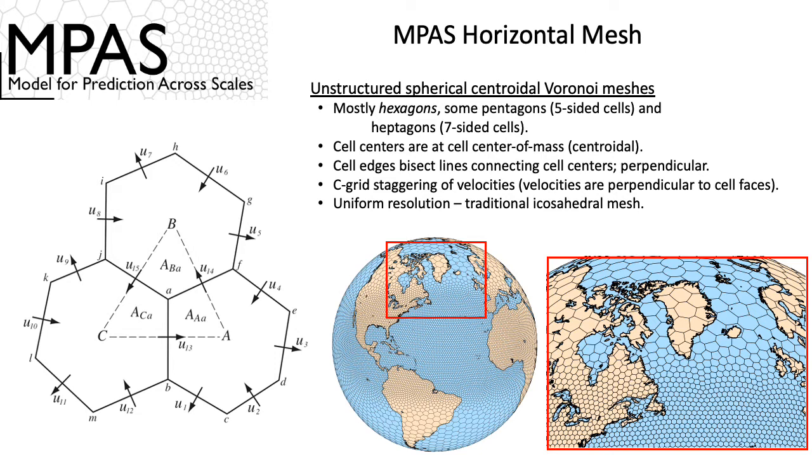This one, as you can see, some of the cells are kind of odd shaped, but this is just a preliminary mesh which we refine further as part of our process to generate these meshes. So ultimately, the mesh cells vary smoothly across this mesh, across the transition regions. Typically, the cell sizes or the distances separating the cell centers don't vary by more than a few percent as you're traversing from a fine region in the mesh to a coarse region.